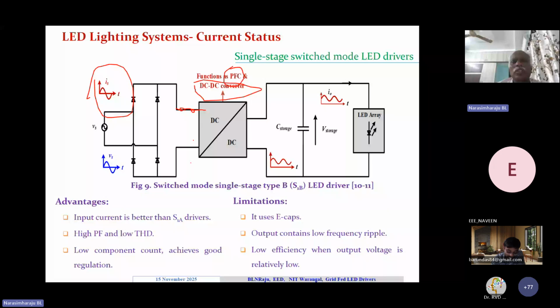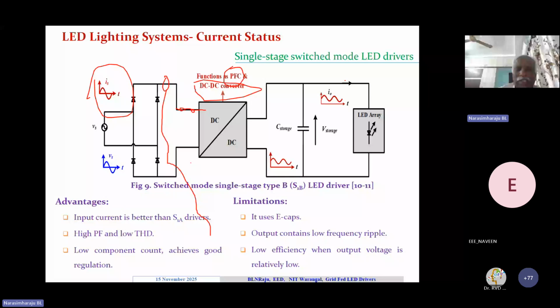So in the case of discontinuous mode, there is an inherent power factor correction possible through this DC-DC conversion process. And if the converter operates in the continuous conduction mode, then we need to go for closed loop control, where we take feedback of the rectified pulsating sinusoidal voltage and also the current, and that needs to be compared with the output, through an error amplifier and comparator.